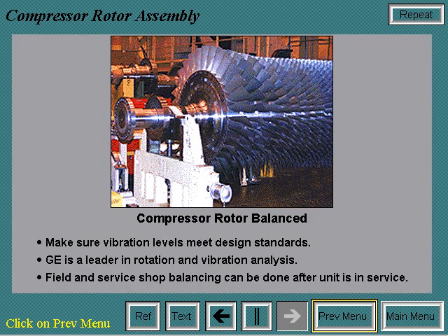Once the compressor rotor is assembled, it is slow-speed balanced to make sure vibration levels meet design standards. GE is a leader in rotating equipment and vibration analysis. Also, field and service shop balancing can be done after the unit is in service.